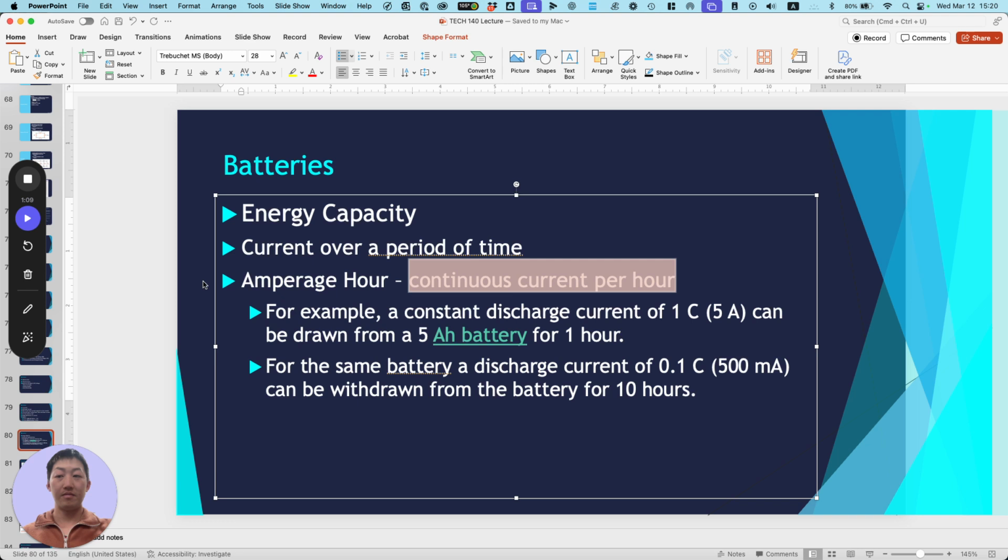All right. Now I'm going to take this multimeter here. What setting do we want to put on here with the multimeter? Direct voltage. Yes, which one is that? That looks like the first one. Yeah, it's the first one, the one with the straight lines. And we're doing DC. It's on auto right now, but if I want to, I could press function and force it. Oh, okay, never mind. What's that? Ranging. Oh, range. Range should just be the volts. You see how it's changing from volts to millivolts? And it's just changing the decimal point. I think it's just function. It's just going to know that's DC.